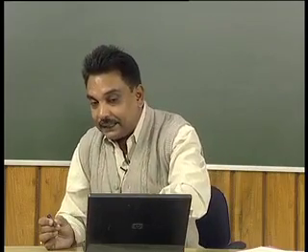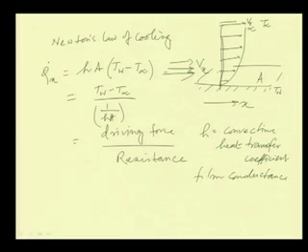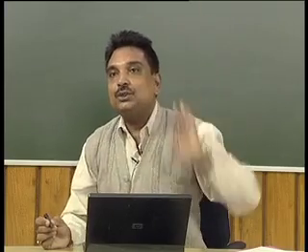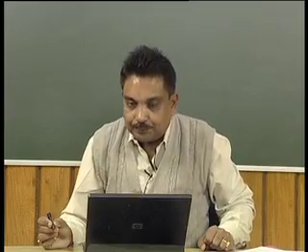So, you can understand that from the surface of the wall till the free stream condition, the heat is being transported by a combined mechanism. One is the very initial stage from the wall to the adjacent fluid layer by conduction, and then from conduction it is gradually switching over to the convection mode.